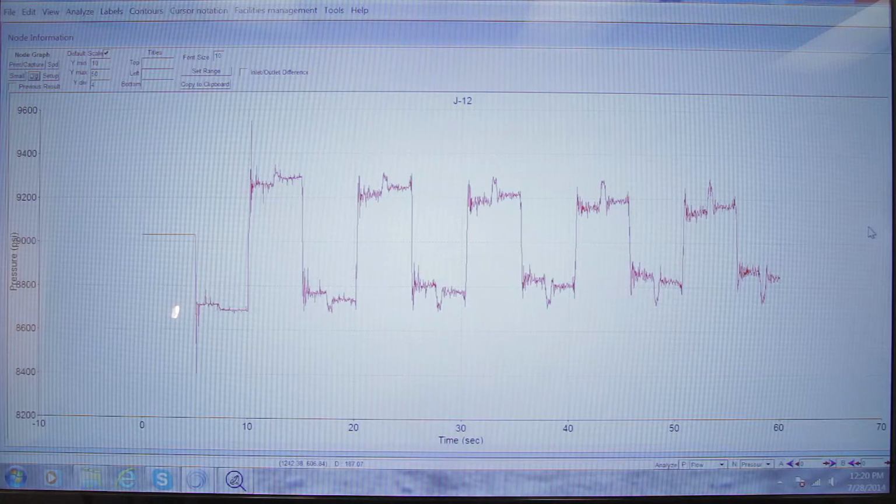And remember, our piping system might be 3 miles down into the earth. And again, it's the same thing with our shock wave. That shock wave is traveling 3,000 or 4,000 feet per second down into the earth and then oscillating back. So again, on our time step, you'll see the negative wave going out, coming back, and then shooting back up to almost 9,600 PSI.